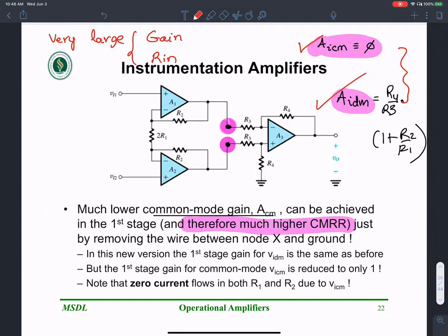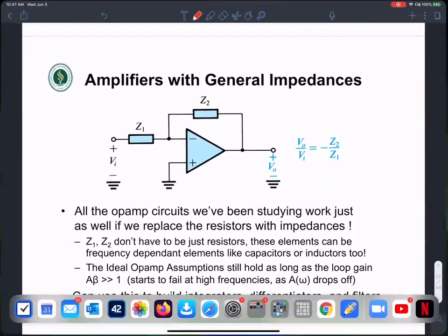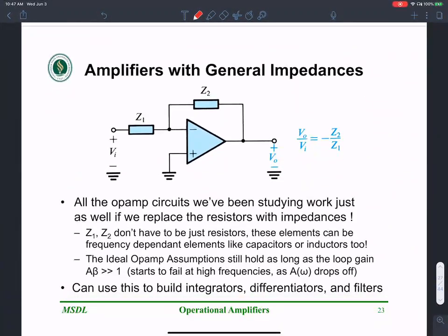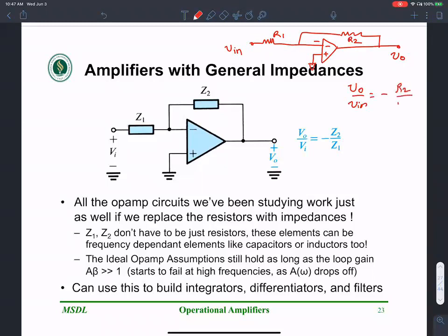All right. So let's see. Now, let's expand the idea of an operational amplifier. This is an inverting amplifier configuration, right? We have seen the idea of an inverting amplifier where there is a negative terminal, and the positive terminal is tied to ground. There is a resistance R1 over here, and there is another resistance, the feedback resistance R2, over there. The output, V output, is taken at that node. V input was over there. The gain, V output over V input, was earlier negative R2 over R1.